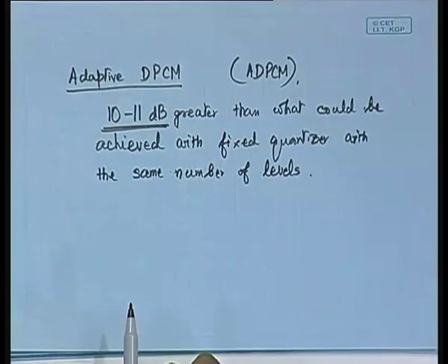And how do we make that adaptive? So, again, likewise, we can adapt it using the feed forward or feedback mechanism. So, we can have a block diagram like this, and for the feed forward, as you rightly understand, we have to transmit the delta n also, not only Cn, but delta n.